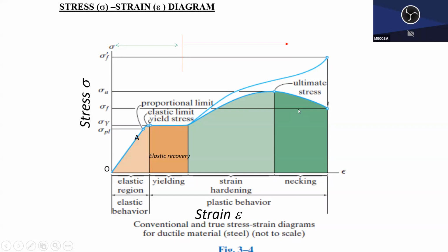Okay, and this part is linear, elastic, right? Elastic means that if I stop applying the force, let go, then the material will shrink down, follow this curve and go back to here, right? Good. But if you keep applying the stress, then you will hit the yield stress.